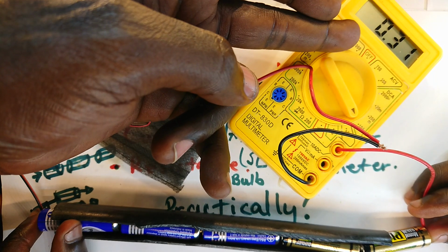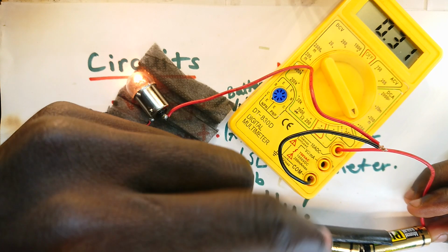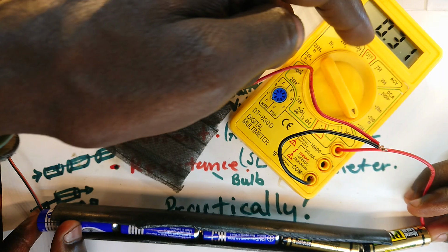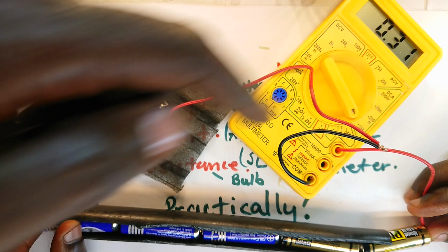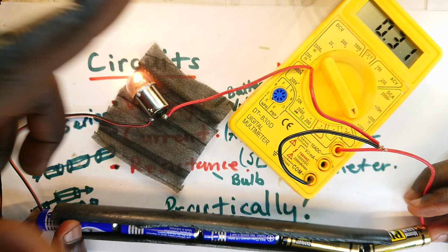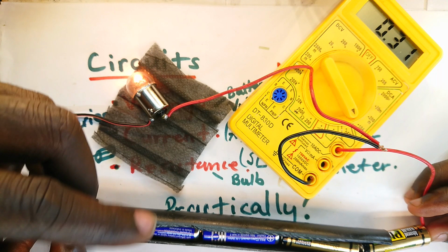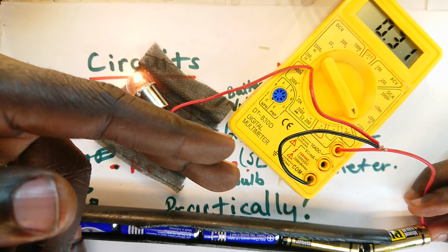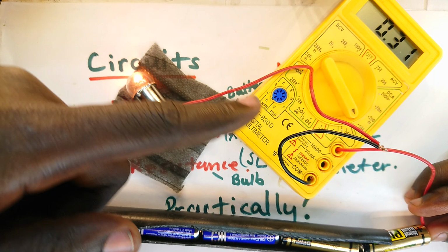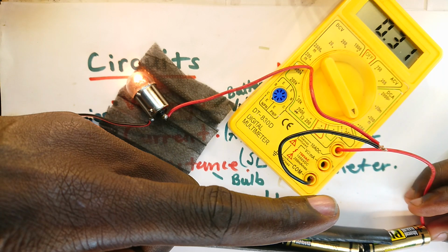So what it is doing is tapping a bit of the current and seeing how big it is, and then the battery inside powers the IC to show you the value. But if it was the so-called moving coil ones, they would consume more current, because the same current that is being measured is also what causes the needle to deflect. Yeah.